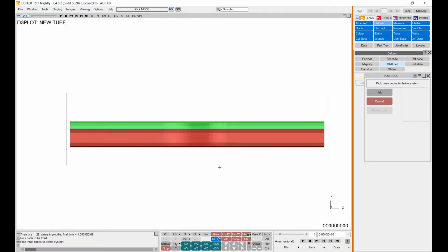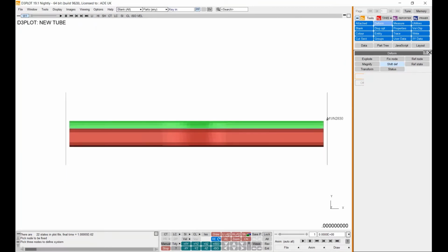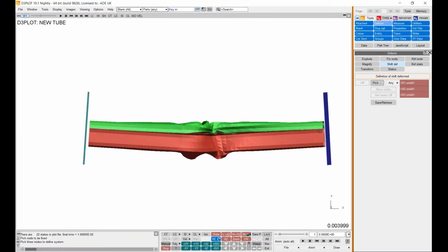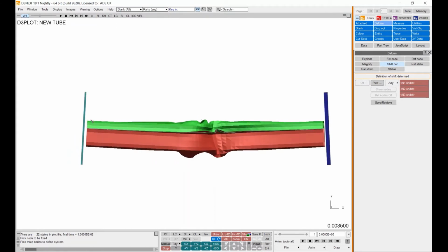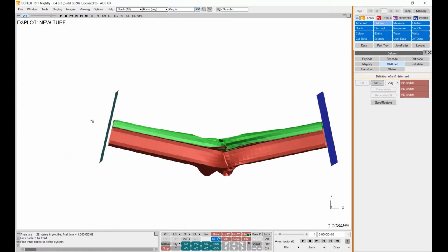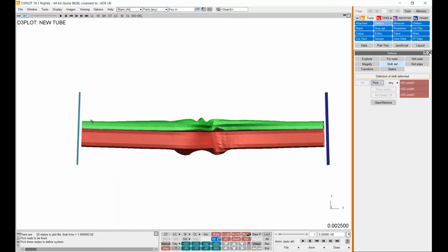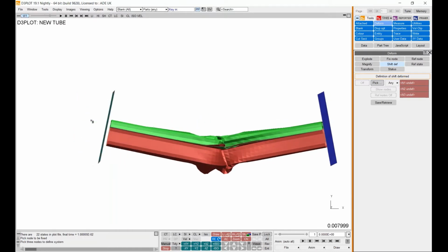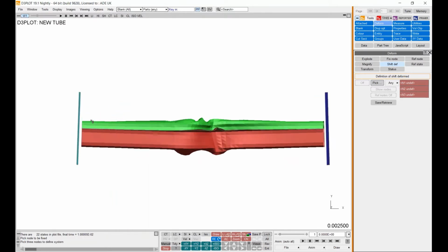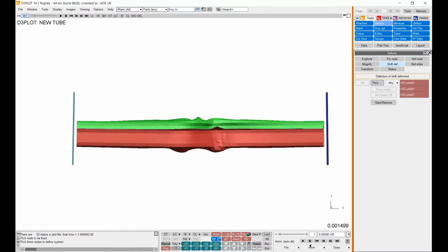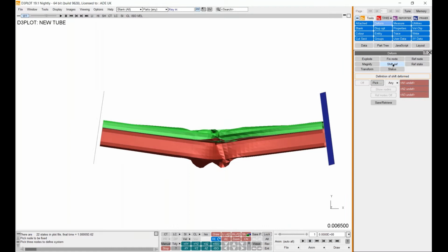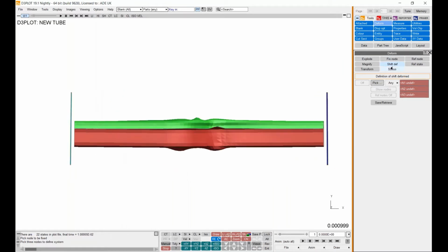So in this crush example here, if I wanted to measure the maximum end-to-end deformation between these two plates, it would be quite difficult to do because they're both rotating. An automotive application of this would be measuring crush, where the vehicle will have likely undergone both translation and rotation. So to turn on the shift deformed option, I'm in this menu here: deform, shift def, and then I